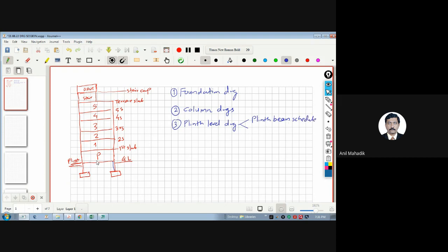Also, all of you know that we start the staircase from this level only, right? Yes, sir. So this is your staircase level like this. So we should give the staircase drawing also at this level only. Then the people can start the construction, right? Here we start our staircase also, and then the staircase goes up. And if there is a lift in the building, does it start from the plinth level, or where does it start? Anybody knows where this lift wall starts?